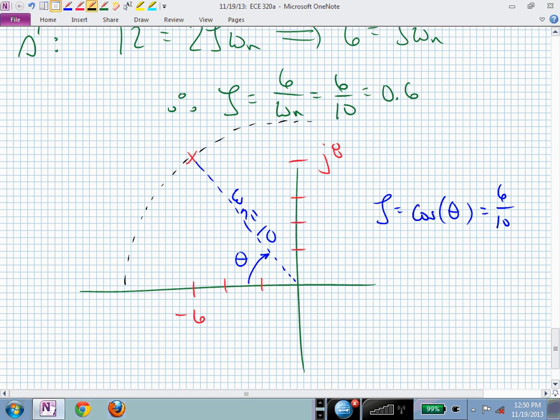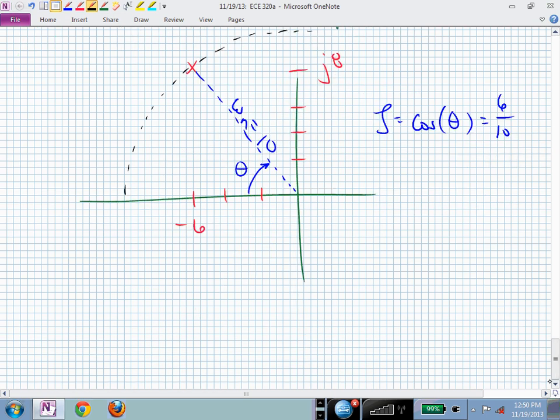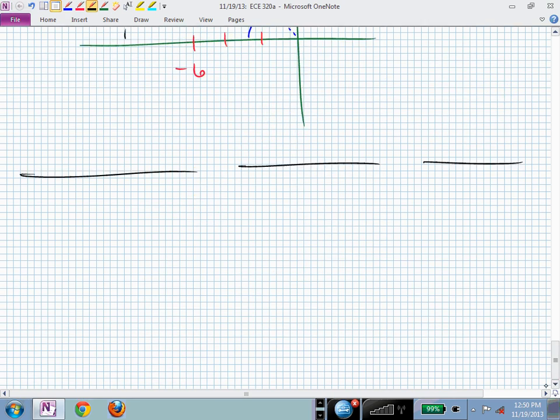So we need to learn how to do linear factors, poles and zeros at the origin, and constant factors to sketch those. Let's now first, before we get too far into this, convert that transfer function into time constant form.